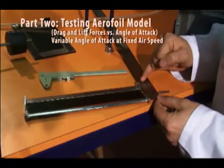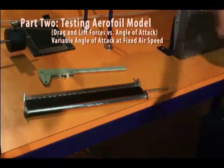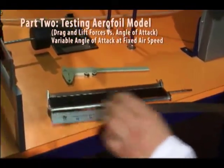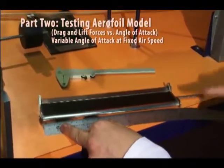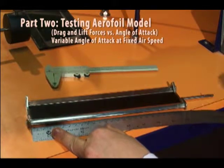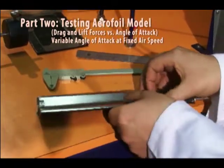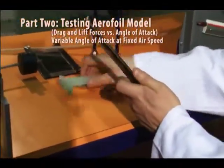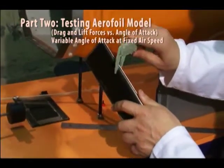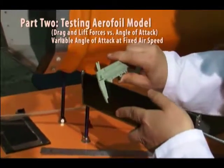Measure the dimensions of the different parts of the aerofoil, including the full angle of opened flap. These dimensions will be used in calculating the projected cross-sectional area. It is important to note that the projected area will change with each angle of attack. Also, for a certain angle of attack, the projected area is different in cases of closed and open flap.